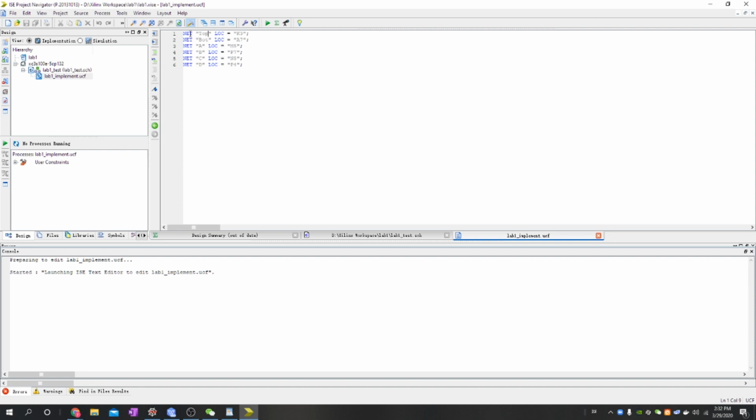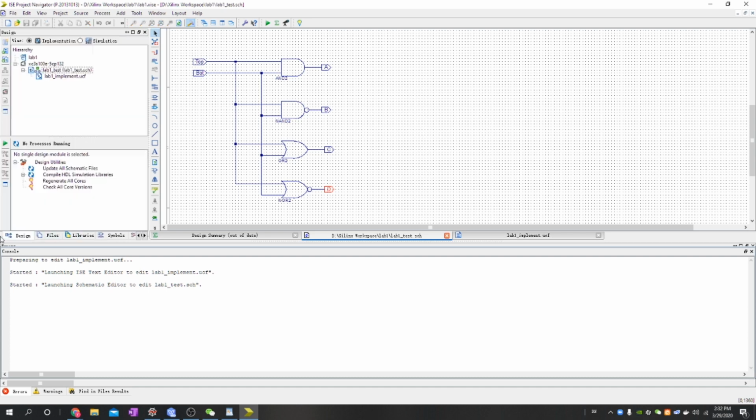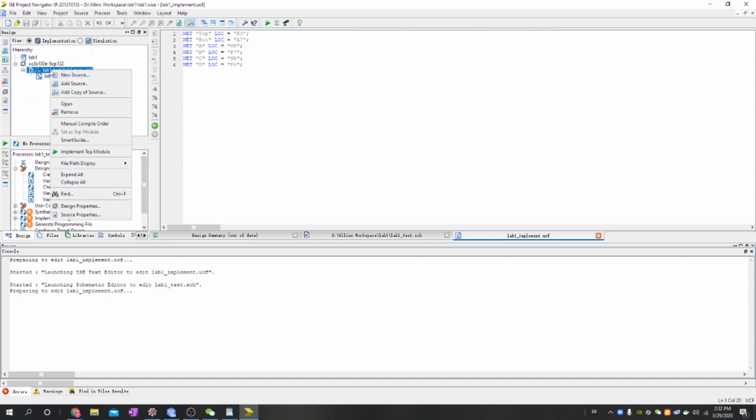will clarify and match the software port, like top, bottom, to the hardware port, like K3, A7. If you have an FPGA hardware board, you can see the K3, A7, this kind of port names printed on the board. Then you know our schematic file's port, our circuit port, top or bottom here, will correspond to the hardware A7 port. Okay. Then select the schematic file to synthesize.